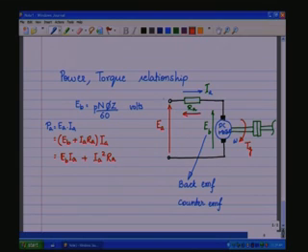So, the power that is drawn from the source, a portion of it, IA square RA, goes off as heat in the armature winding resistance RA, and the remaining portion EB IA is the one that goes into the machine.